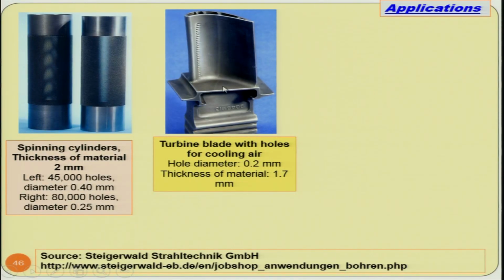So, you need the cooling holes, and these cooling holes are normally micro sized holes, but thousands and thousands in number. To machine these holes in very hard materials like turbine blade material, industrialists earlier normally used the electrochemical micromachining process. Later they started using, to some extent, the electric discharge micro drilling process, although it is a thermal process, it has some advantages but many disadvantages also. So, they have tried the turbine blade using electron beam micromachining.